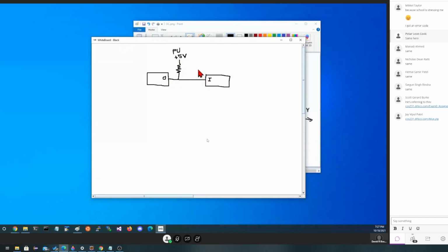And so by default, he's going to see plus roughly 5 volts. And you'll continue seeing that until this guy produces a 0. If this guy produces a 0, of course, current can flow through the resistor to 0, he'll see a 0.